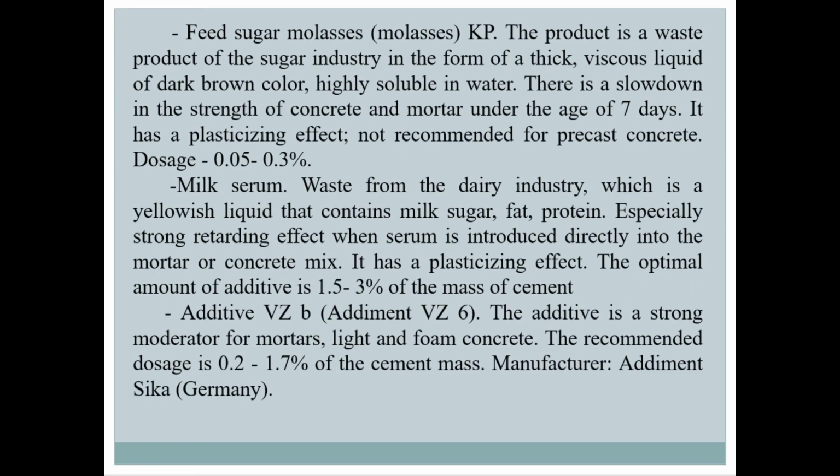Feed sugar molasses KP. The product is a waste product of the sugar industry in the form of a viscous liquid of dark brown color, highly soluble in water. There is a decrease in the strength of concrete and mortar at the age of 7 days. It has a plasticizing effect, not recommended for prestressed concrete. Dosage